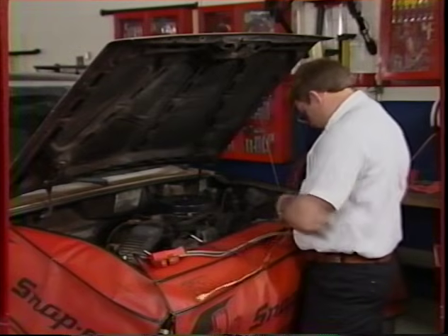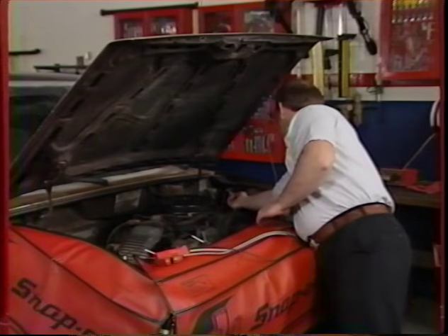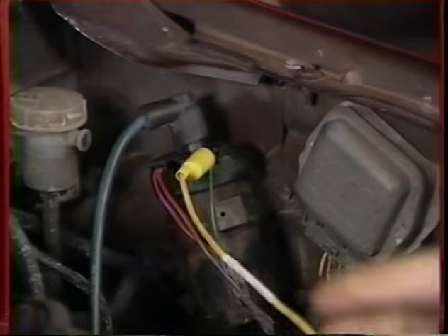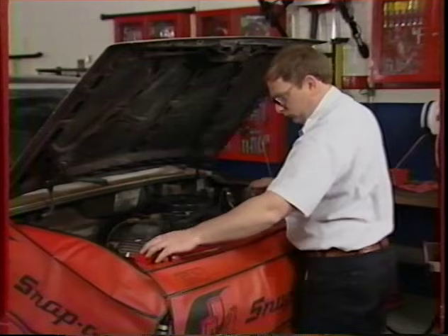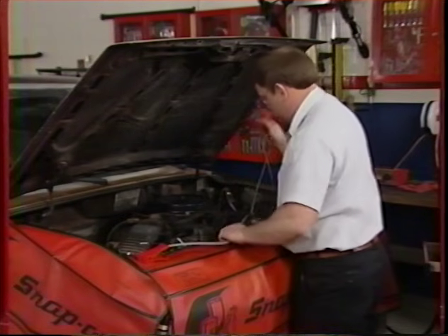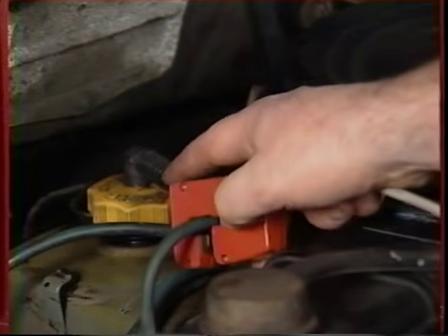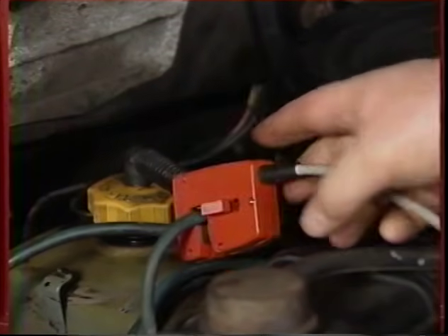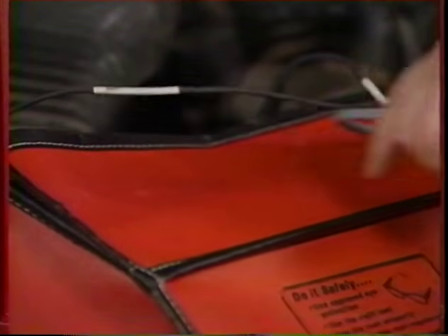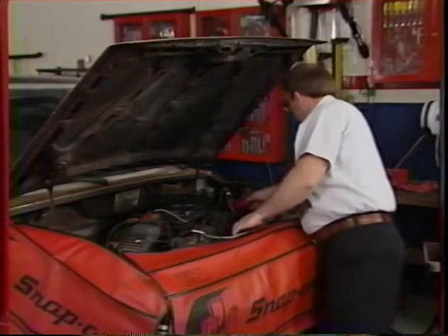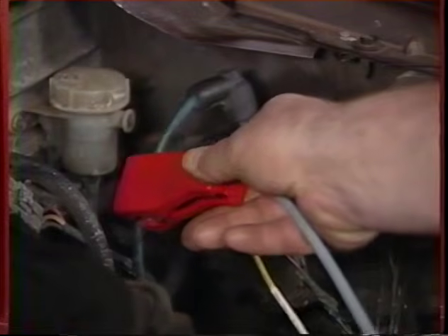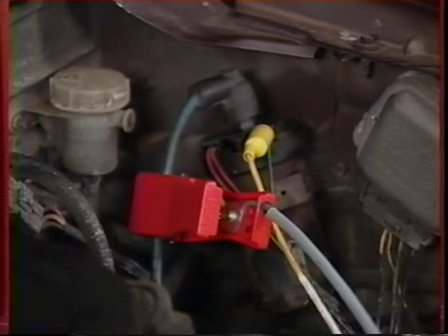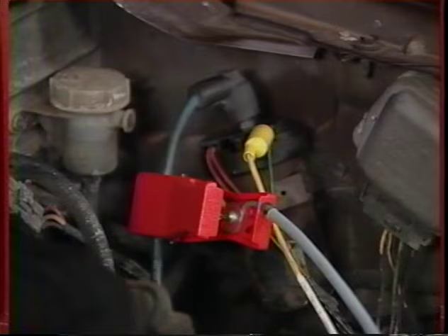The yellow lead picks up signals from the primary ignition system and the fuel injector. It can be attached to the tach terminal, negative side of the coil, or fuel injector harness. The red inductive lead goes over the number 1 cylinder spark plug wire. The secondary adapter will go over the coil wire when there's an external coil, or will attach to the distributor for internal coils. Special adapters are available for GM, Honda, and Toyota ignition systems.